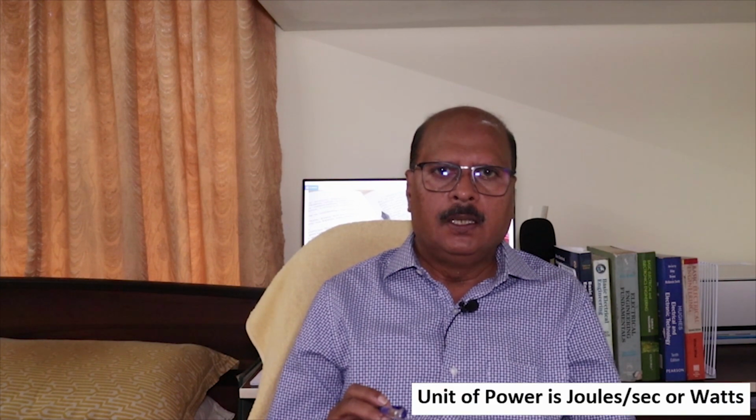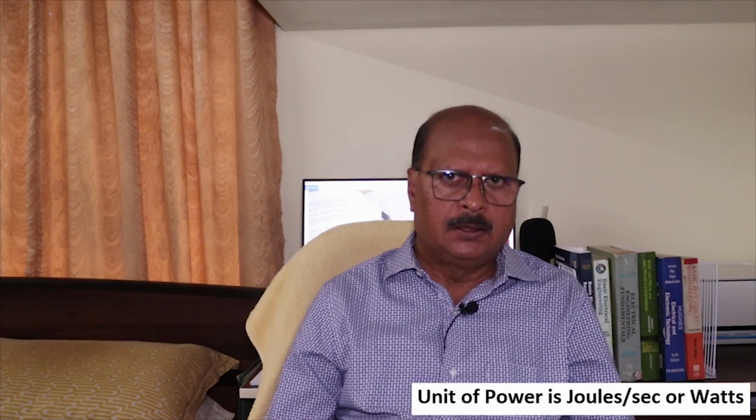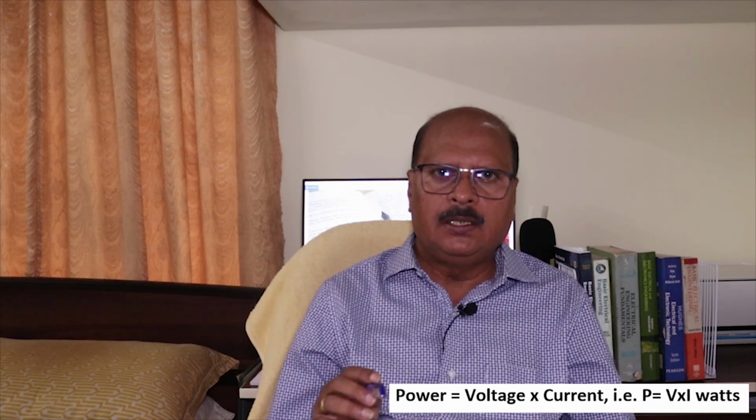The rate of doing work is called power P. Its unit is joules per second, or watts. The power in a circuit with voltage V and current I is P equal to V into I. Power is equal to voltage into current. When a voltage of 1 volt is applied across a conductor and causes a current of 1 ampere to flow through it, the power developed is 1 watt.